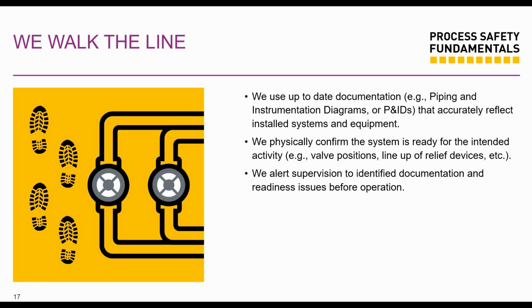The line was blind flanged before, and you didn't know that blind flange was removed. You go in there and you start up, or maybe some people were actually working on that line, and they removed the blind flange, and you didn't know. You start the line and you have a leak of hydrocarbons. A walk the line could have caught that, or a bypass valve.